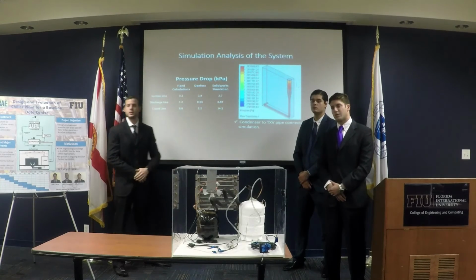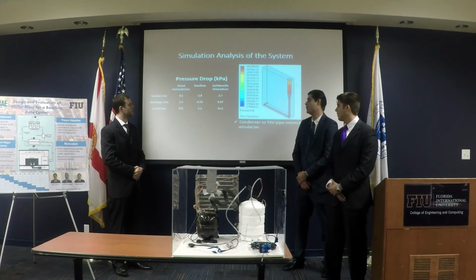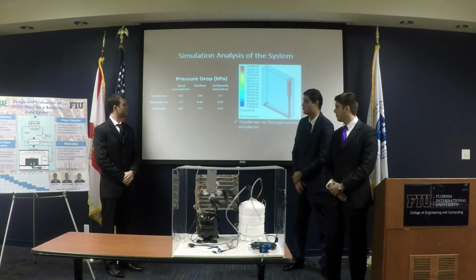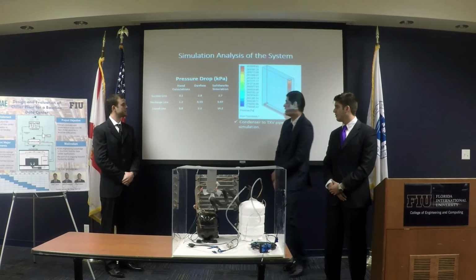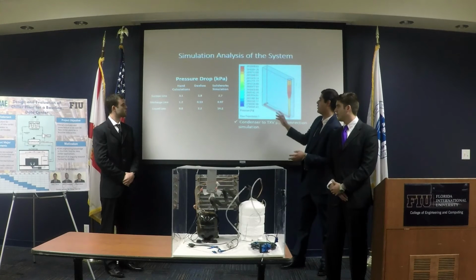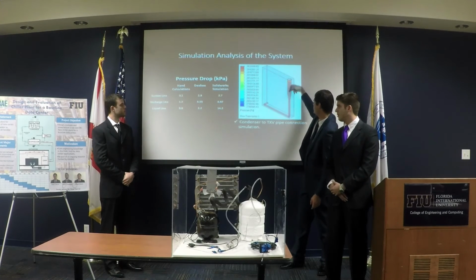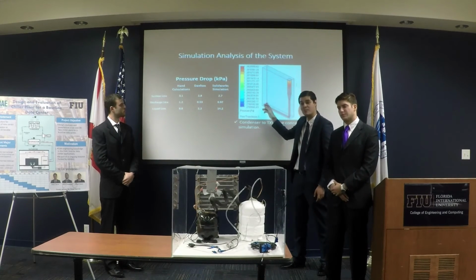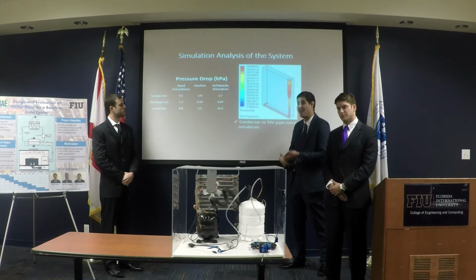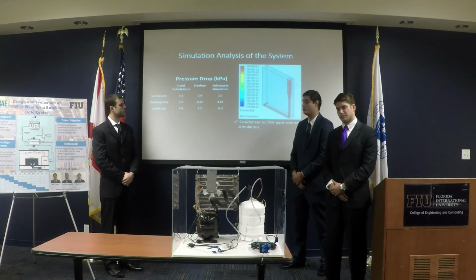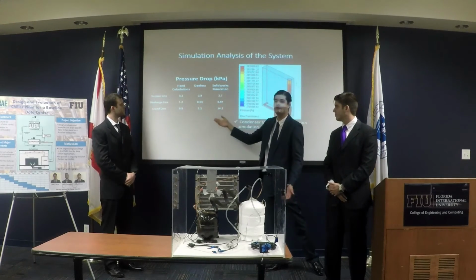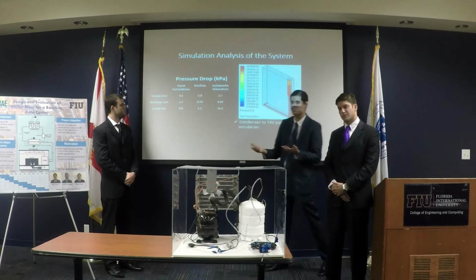So which ones did you use, actually? Which measurement did you use? The ones we're taking are the highest. However, the pressure drop is insignificant. The highest pressure drop is in the liquid line, and it doesn't really matter because it's not connected to the thermal expansion valve, and the purpose of that valve is to lower the pressure a lot, like 28 bars. Over here, it's just 0.14 bars, so it's insignificant.